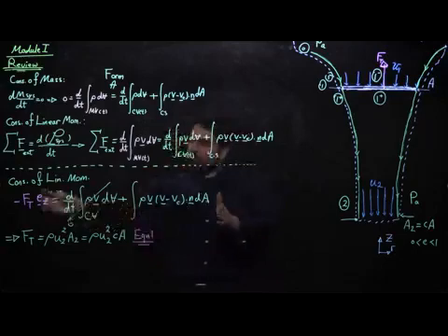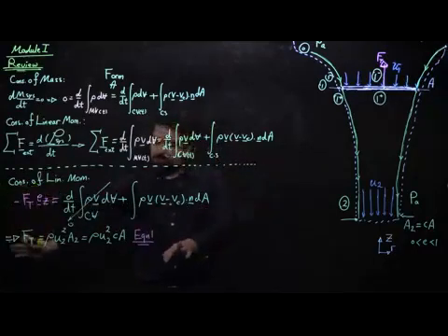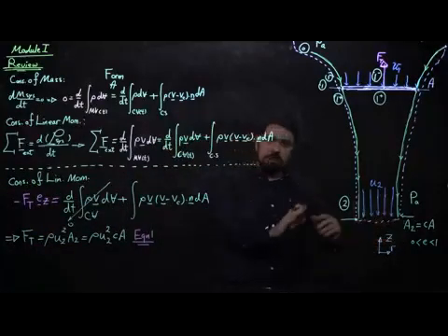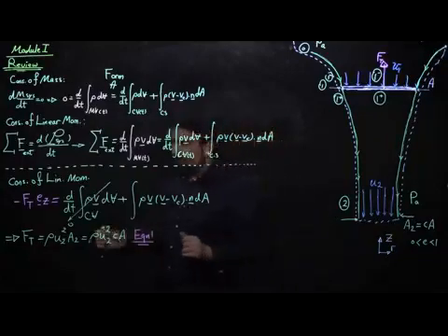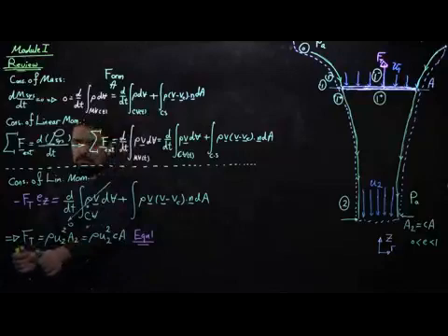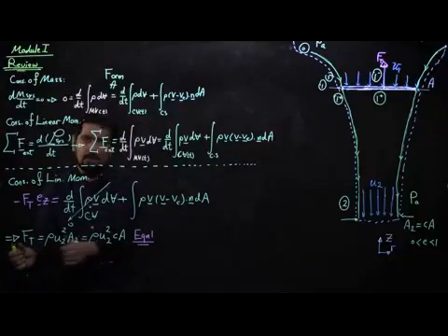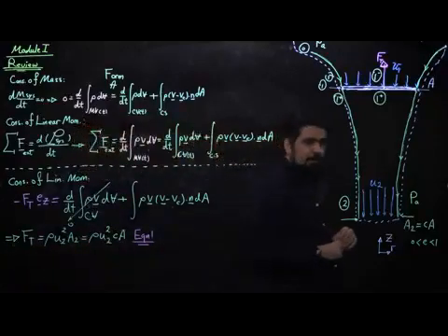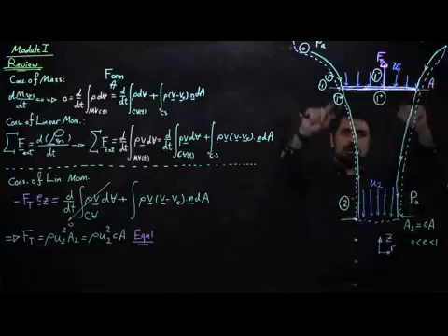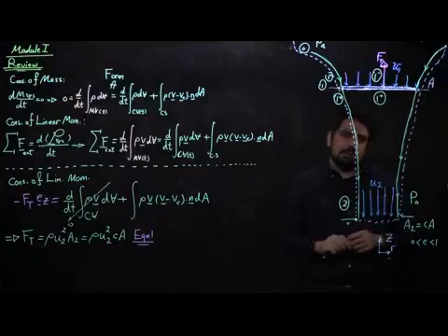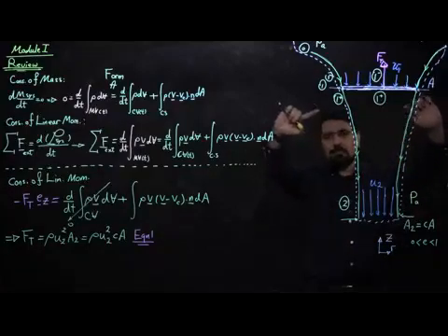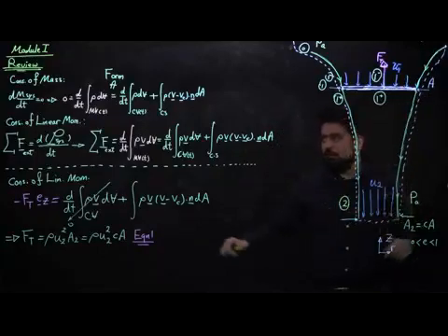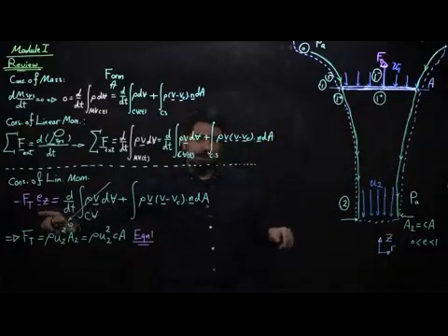This was one equation. We used conservation of linear momentum, and we tried to use some of our ideas about flow. Somebody may say, oh, wait, you really didn't talk about pressures acting on this contour volume. You have a certain pressure field around it. But again, you can easily see that pressure almost all around this area is nothing other than atmospheric. So when you take atmospheric pressure, the horizontal components may not be atmospheric, but they don't give me any component of momentum in the z direction.